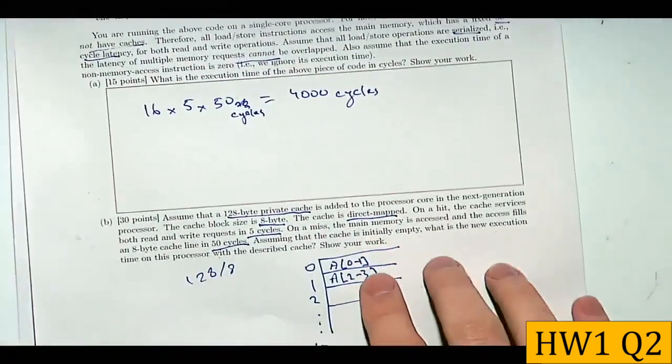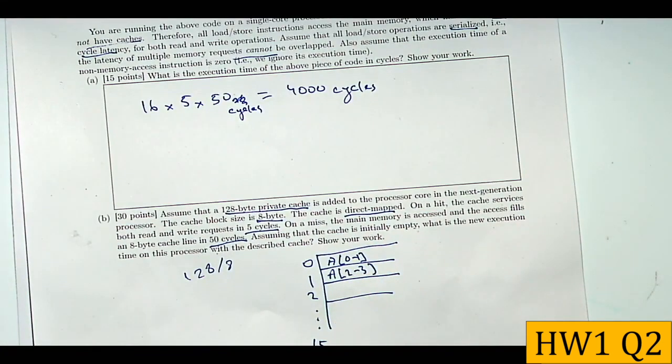We had those conflict misses, right? So we have to have a design that will avoid the conflict misses. And the best thing you can do here is just to turn this cache to a design where you have two ways, right? In that case, you can keep both B0, B1, and A0 and A1 together in the cache, and you'll avoid all conflict misses.